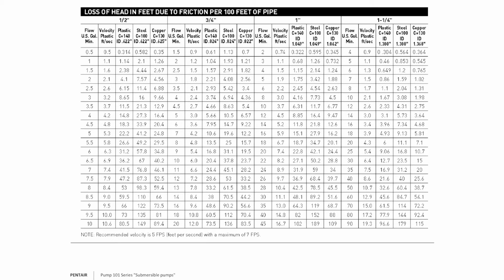Now, not to get into too much detail, but we're looking at a friction loss chart here. So quickly we're going to look at 10 gallons per minute, and we're going to look at 1-inch pipe. At 10 gallons per minute in 1-inch pipe, we see the velocity is 3.7 feet per second, so we're not worried about water hammer. We have good velocity.